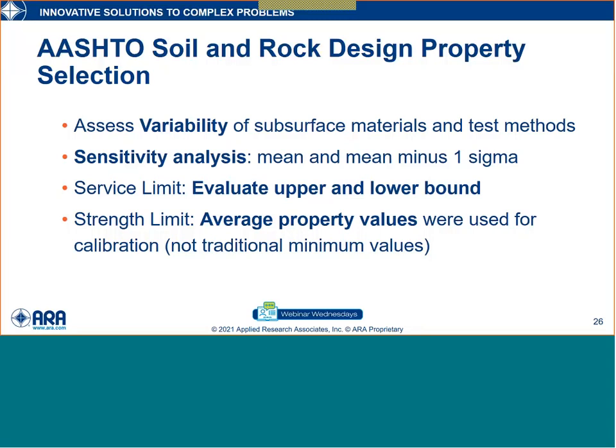Now, historically, where have we goofed up here? We didn't follow this guidance. As a community, we gravitated to the lowest data point in the body of knowledge of the strength data that we had for a particular project. That's not appropriate. When asked historically why did you do that, the designer would robotically answer, it's a conservative approach. Well, it may not be the most conservative approach because the property that you pick might be an outlier. It might be unconservative. And if you're excessively overly conservative, you don't want to be there because you won't be called by the civil specialist, the structural specialist, the hydraulic specialist.